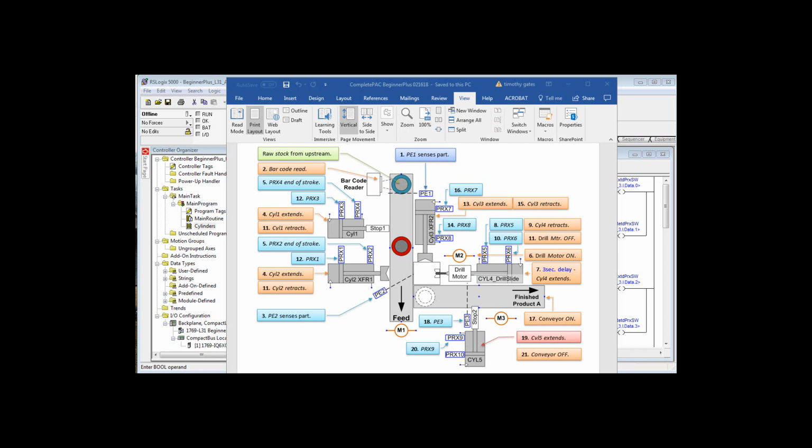Now we may want to put a delay in between 8 and 9, meaning, remember that these proximity switches, Hall effect sensors, whatever they are, are adjustable, meaning that you can adjust them at the ends of stroke, retract and extend.